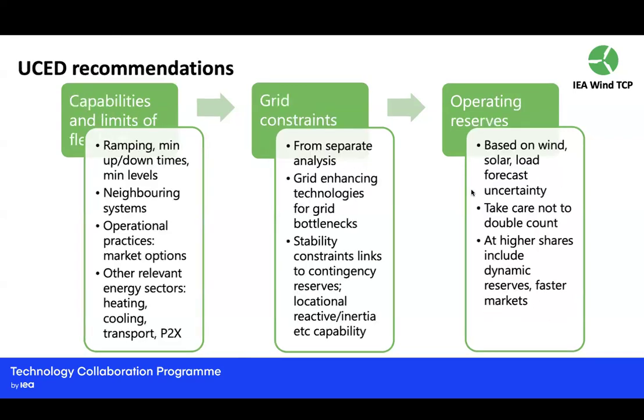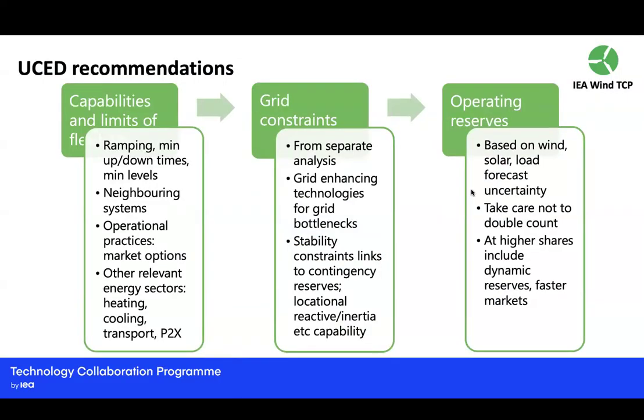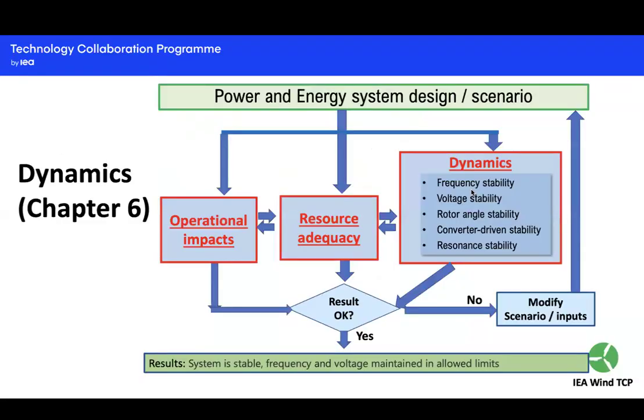And then for the operational simulations, you really need to include everything that impacts flexibility, because you're simulating more variability in your system, and hopefully also include something for the grid constraints. There are also recommendations on how you do operating reserves, to make sure that with increased levels of wind and solar, you also have increased levels of reserves that will help to operate the system. And then we come to